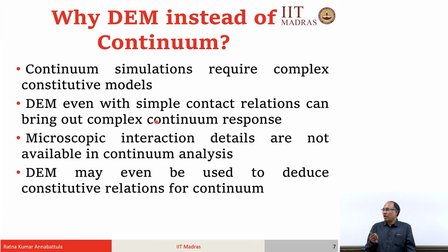But although the constituent particles are, say, linear elastic in nature, the macroscopic response will not be linear elastic. It will be some complex nonlinear response. So, what will be the constitutive response of such a granular assembly is something that we can deduce from DEM. You can do a laboratory surrogate experiment using DEM and then deduce the macroscopic constitutive relation that can be simply plugged into your finite element model.